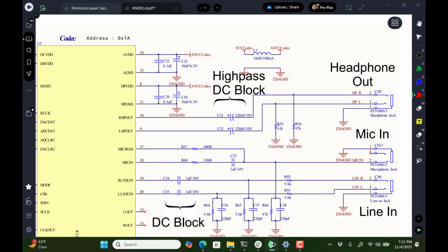You'd be able to understand in particular what this time constant is. This is just a coupling capacitor. So in electronics, you learn about how 1 microfarad, if it's a high enough impedance, has a really low frequency roll-off. Because what does a coupling capacitor do? It blocks DC, but it actually rolls off really low frequencies like bass notes or something, right? So you could calculate that time constant, and then this, what this is doing, 220 picofarads and 5.6K. Kind of interesting. I'm not asking you to do that here.